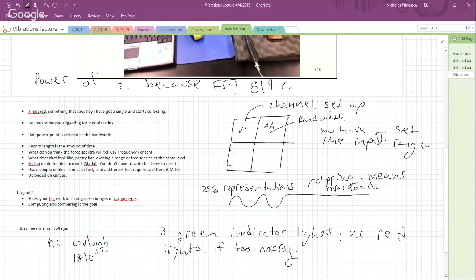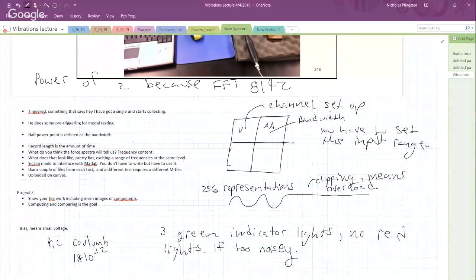This also has a zoom feature. What you'll notice when you start trying to extract damping ratios is that when you look point to point, the resolution in the frequency range is not as fine as you'd like. So we could use a zoom-in feature, so you could have hundreds of data points around each peak instead of just maybe a few. We're not going to use that for our purposes today.